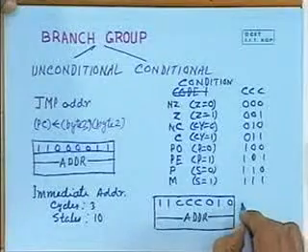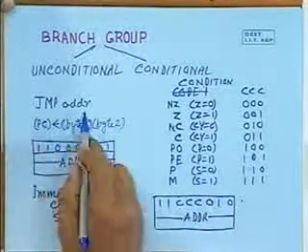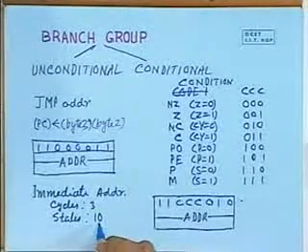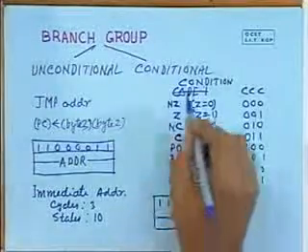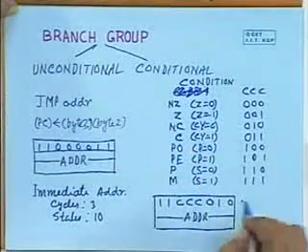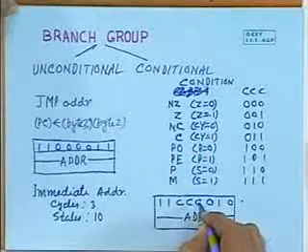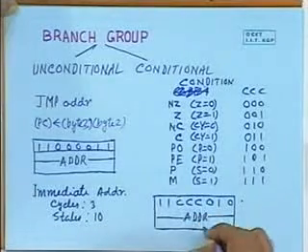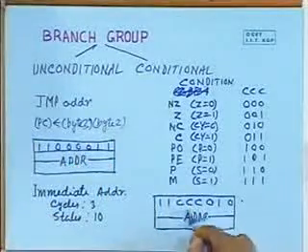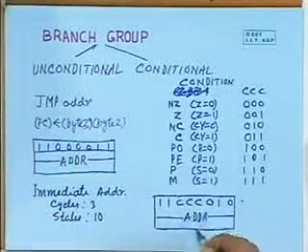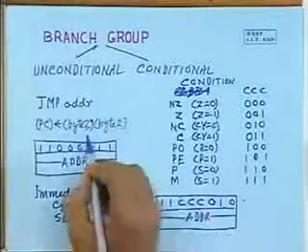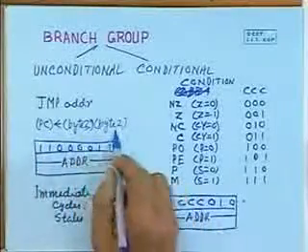One thing you must notice here, in case of the unconditional jump, the time required is fixed. The number of cycles is 3 and number of states required is 10, which is not true in conditional branch instructions. For example, whenever the condition is not satisfied, obviously you will not fetch this address and jump to a new location. You will not perform this operation. On the other hand, when this condition is satisfied, then you will fetch these 2 bytes, which is the address which will be loaded in the program counter. Then the time required will be different.